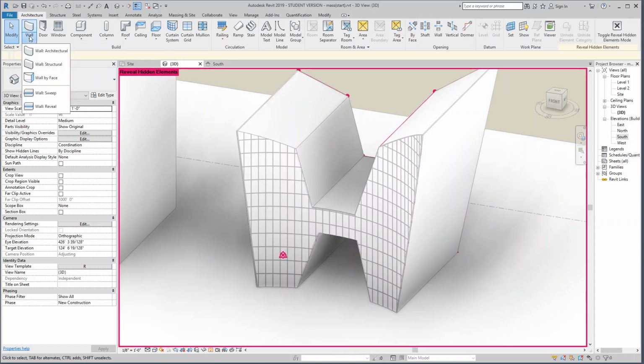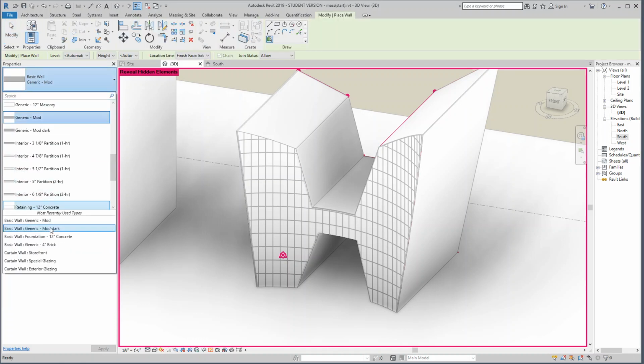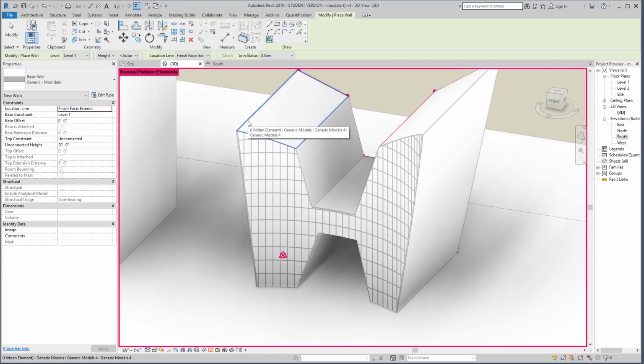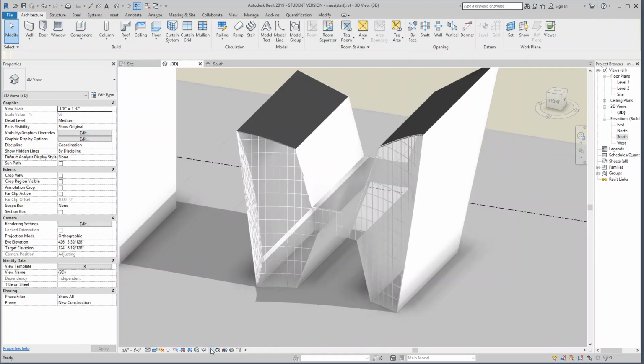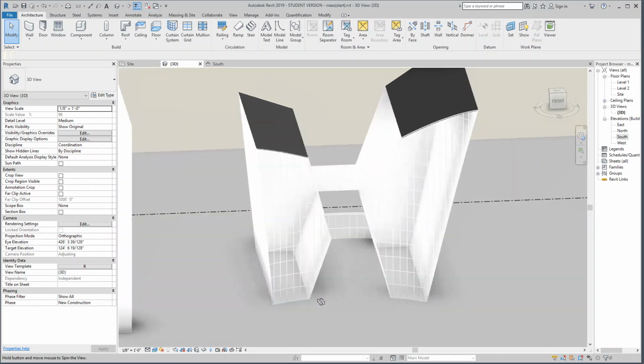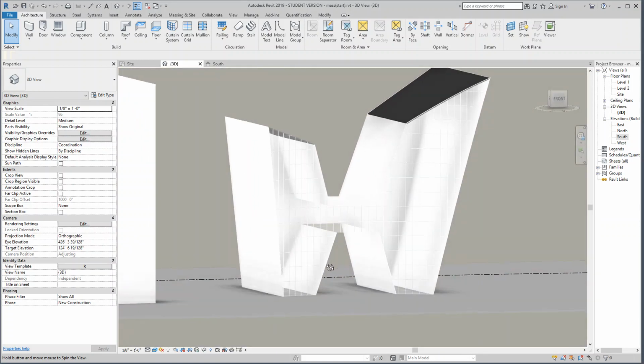And I'm going to go back to the wall tool, wall by face, and select the dark surface that we have, and then go ahead and pick those two top surfaces. And then I'll click modify and I'll turn the light bulb off. And then we have two top dark surfaces on that. And I'll hold the shift and mouse button and we can roll around and we can see how we started to create those kind of elements for the building.